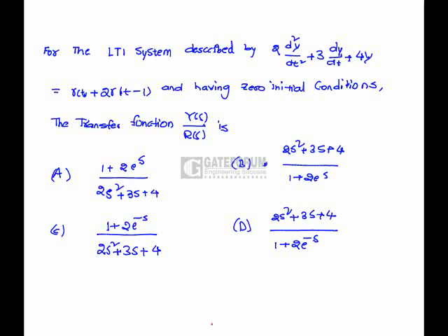Here the question is, for the LTI system described by the second order differential equation having 0 initial conditions, what is the transfer function? We know that the transfer function, which we derive using the Laplace transform, works only under 0 initial conditions. So we can apply the Laplace transform in order to get the transfer function here.